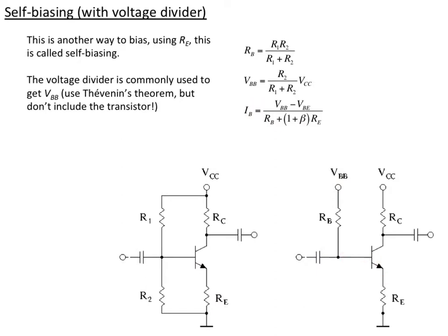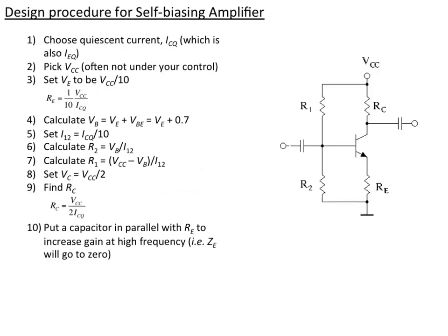Then we drop through the transistor. That gives us the VBE term. And finally, that base current combined with the collector current, beta times bigger, flows through RE, and that gives us the term in the bottom. And we'll notice that the base current here depends only slightly on beta, or HFE in this case. And so that's how self-biasing works to control the effect of beta and temperature.